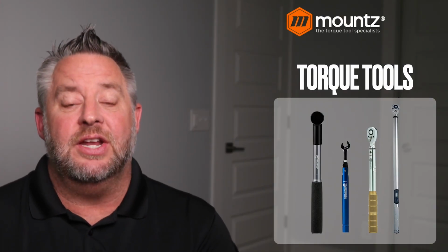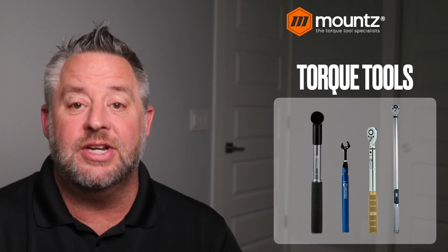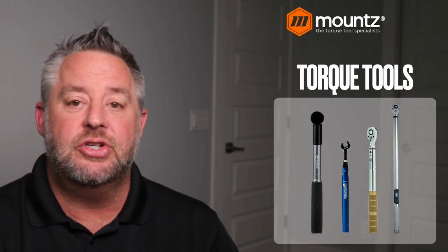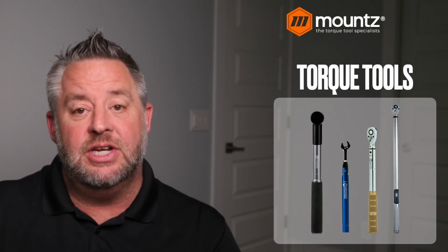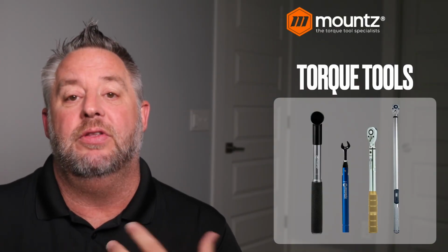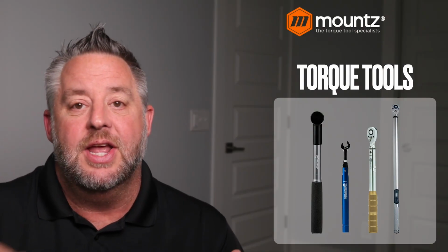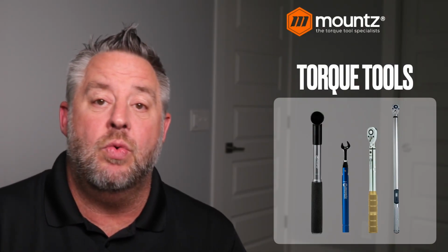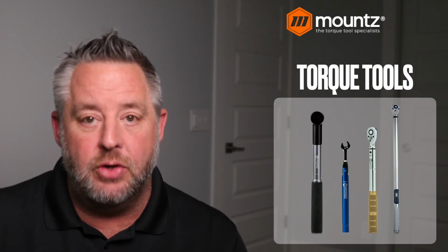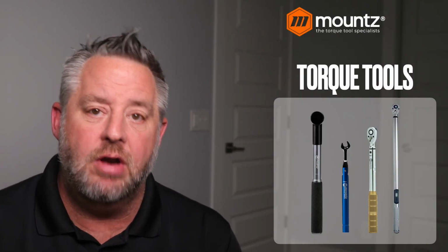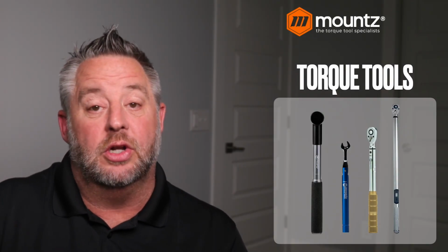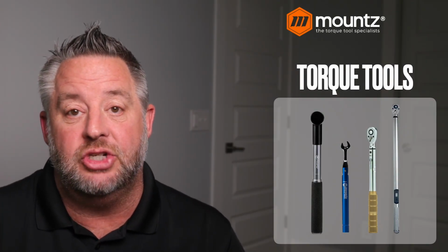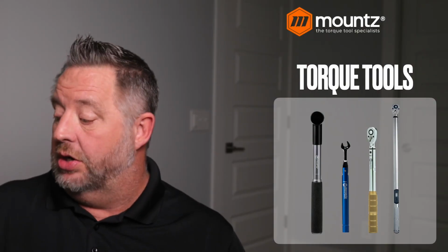Now, the digital wrench will signal when torque is achieved. So you can set a preset value in there and you pull that until you hear the beep of the wrench and then release it. Now, there's no way to stop you from pulling too far on a digital wrench. But again, it's going to alert you when torque has been achieved for what you are looking for.